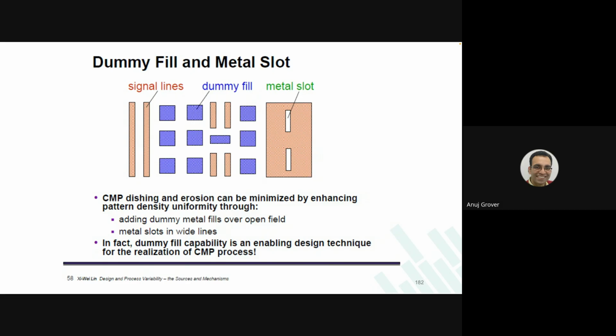Yes, you can think of ways to geometrically arrange your layout in such a way that you can still save area. So area remains a diamond, but if you have no other alternative and area has to go, then area has to go. But matching has to be ensured because functionality is above area. If something is not functional, what will you do with the area? Are you with me? If you do not match well, it can lead to loss of functionality. Forget about the diamond, you will not get it at all. Is that okay?